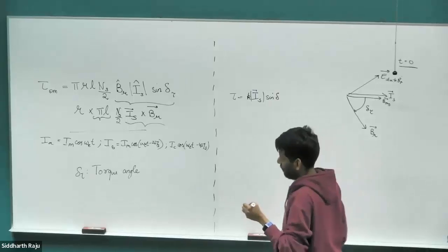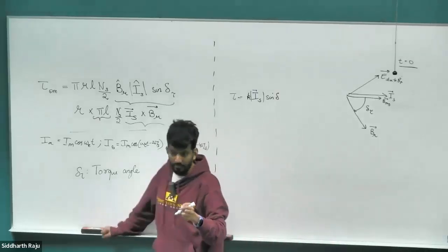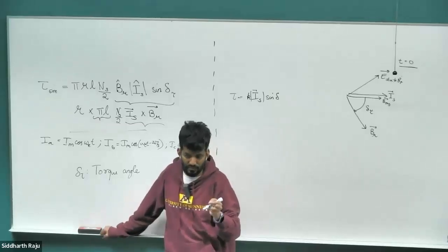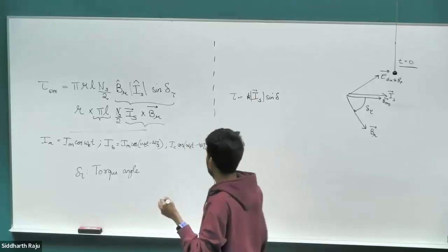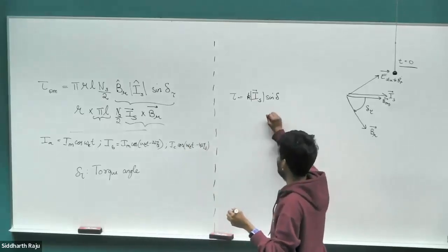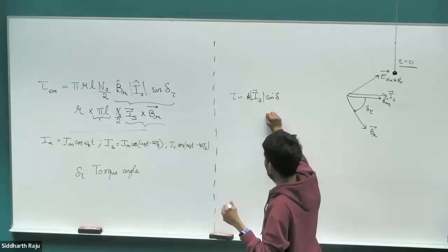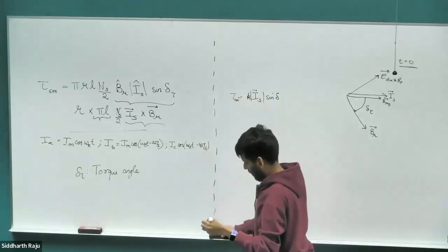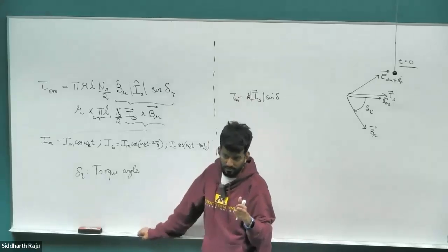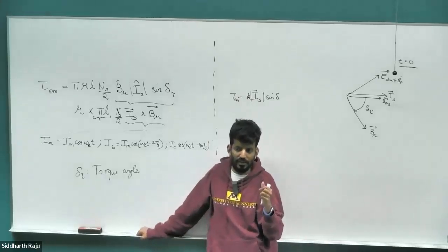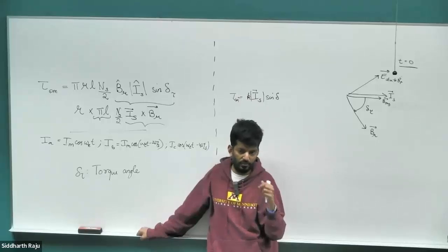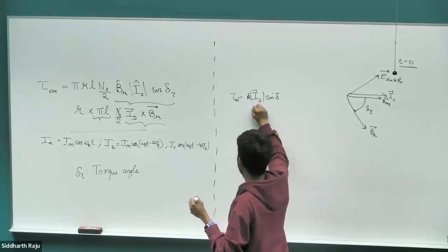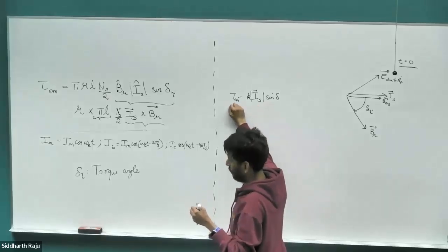Now our objective is to run the drive as efficiently as possible. In particular, when you have drives in electric vehicles that run off a battery, efficiency matters. Every single percentage matters quite a lot because it's a lot of money to increase the capacity of a battery. So if you want to run a motor efficiently, you want as low a current as possible to generate as high a torque as possible, because with higher current you have multiple losses. You have the core losses, hysteresis and eddy current losses, as well as the copper losses, I squared R losses from the stator resistance. So if the current increases, those losses increase. So you want to keep this current as low as possible to generate the maximum amount of torque you want.